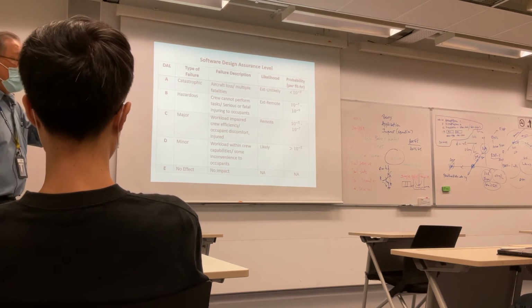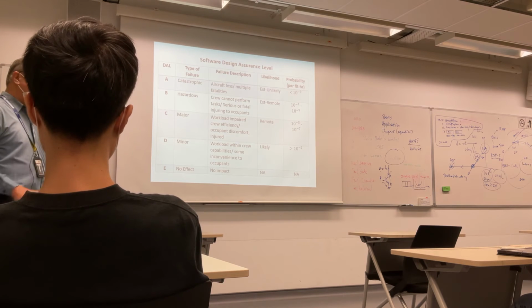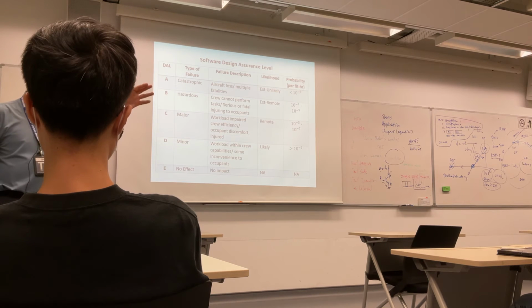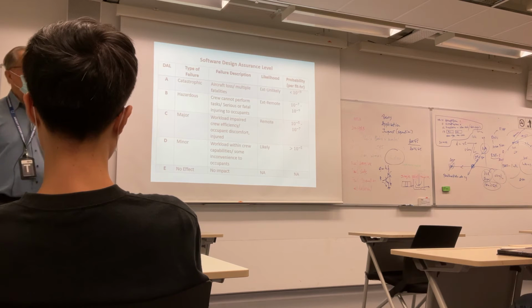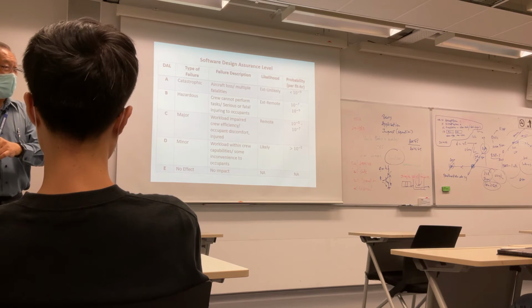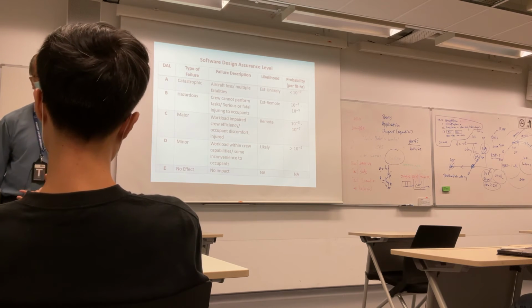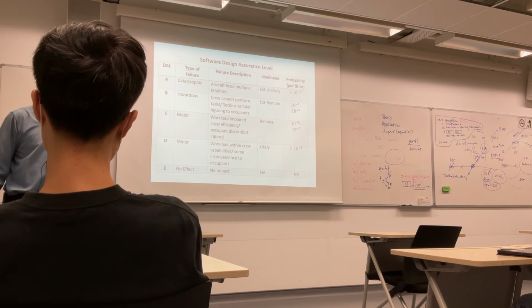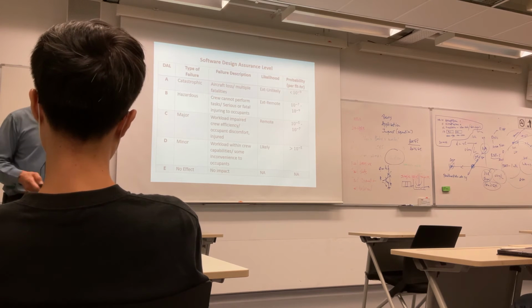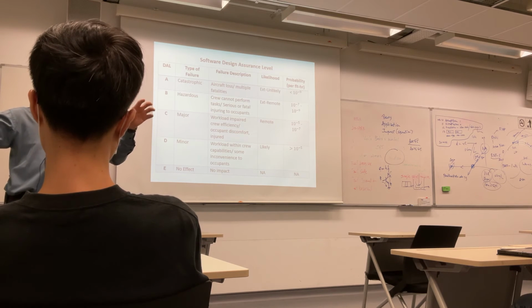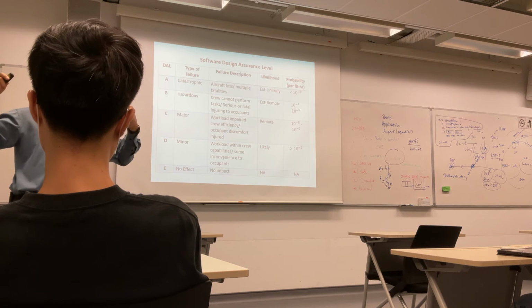So Boeing, somebody cheated the system and classified the MCAS system under C. That's why they designed a single point failure. That means only one of the AOA, angle of attack, sensors will feed information to the MCAS computer. So when that AOA failed, it gave the wrong information to the MCAS, and that's why the aircraft crashed. On investigation, they found that it was violated, because it's supposed to have 2, since the flight control system is supposed to be under hazardous.